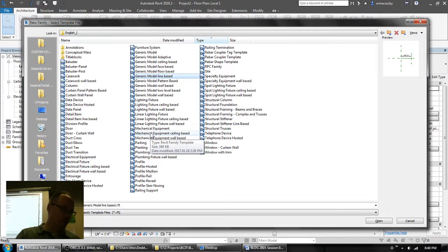Now you don't have to open it, but that's where these 2-pick families get started. So they're meant to be dynamic length families driven by a length of something in your project so that you can infill between those two locations with something.